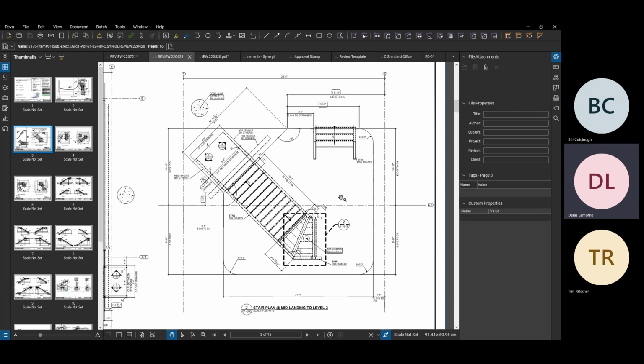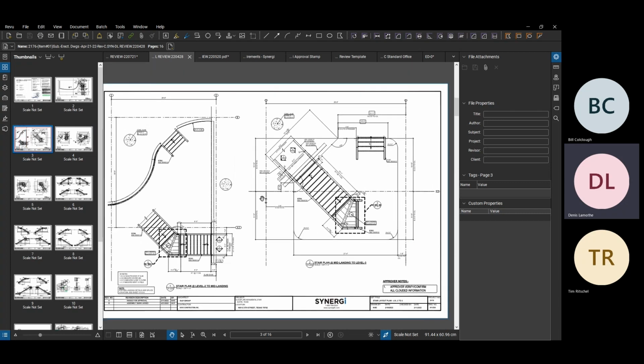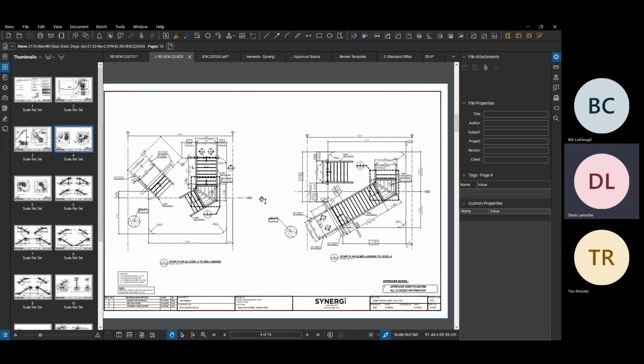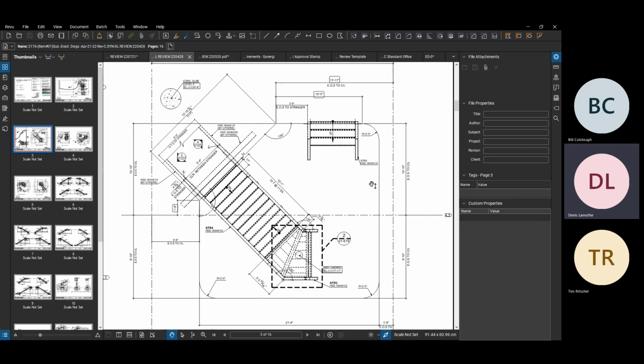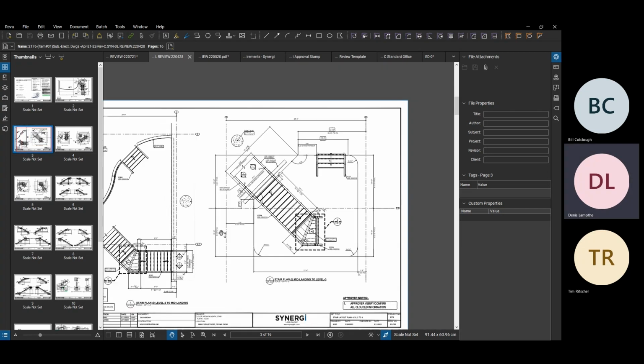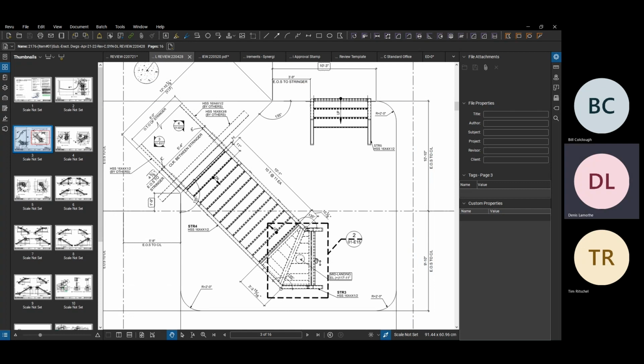Check also, and this is something that I've seen happen, unfortunately, check that the design of the stair matches, in principle, what's on the architecturals, or at least what was discussed and reviewed in the design assist. And what I mean by that is the shape, obviously, hard to miss that, but also the quantity of treads and risers that we have in a flight or in a run of stairs between landing and floors or overall.